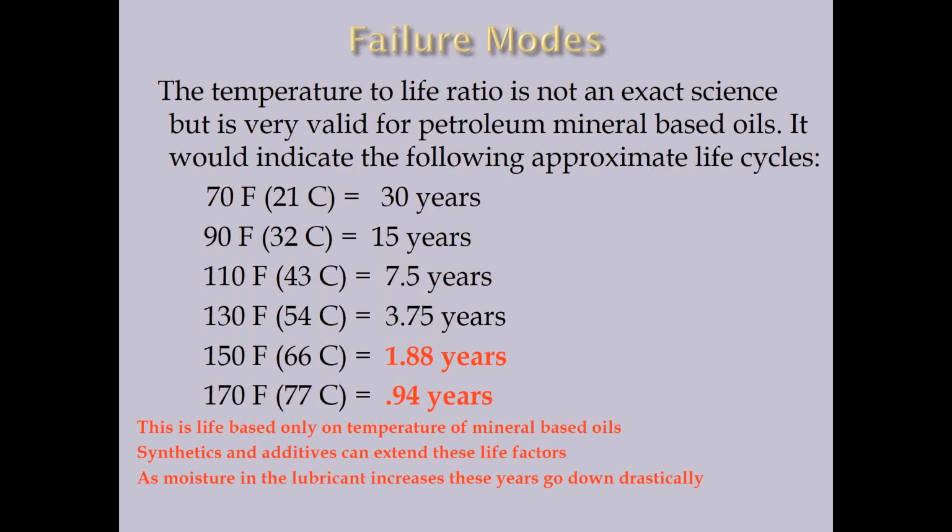So if you have things that are running at high temperature, and also another key point here, the first one in red, these are factors on mineral-based or petroleum-based oils. If you have synthetics and different additives, we can extend the life, like in petroleum-based oils. If there was a way, and there will be a way in a couple of years, we could add the oxidation additive in there and keep that oxidation additive level up. The lubricant would last longer. But synthetics will run at a lot higher temperatures than what I have here, and they'll last 3 to 5 times longer. So if you have high temperature applications, it's a very good reason to switch your lubricants to synthetics.